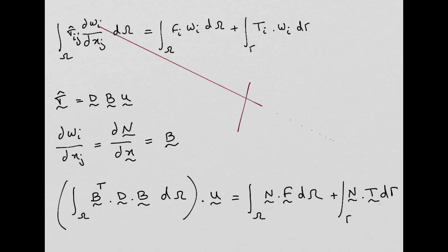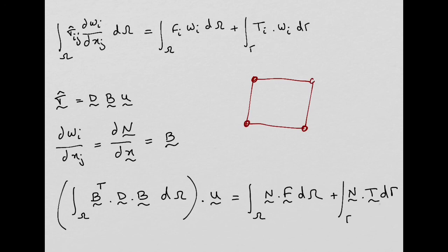For example, when you have a quadrilateral element, it's quite common to have nodes at the vertices of the quadrilateral, 4 nodes, and then inside the element you have, for example, 4 integration points. The location of these integration points in the element is very well defined. The reason why you have these integration points is to do these integrals.